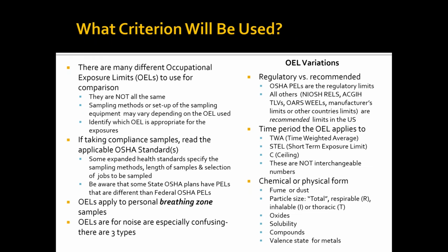because I think it's really important that you decide right from the get-go what exposure limits you're going to use. And you'll see as I go along in the presentation why this is so important. Many of you may know that there are many occupational exposure limits out there. And sometimes they're confusing. In fact, often they're confusing. They're contradictory. They don't all say the same thing, and it gets to be quite confusing. So there are a couple of points I want to get across here.